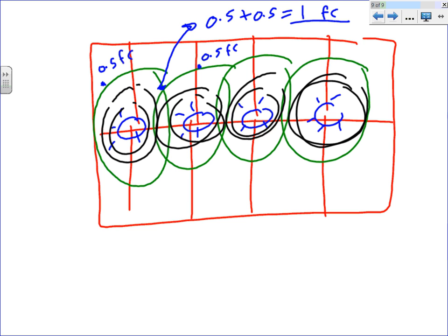The same token could be at this point, Mr. Rabab, right here. If I want to find the foot candle based on these curves, I would go 0.5 plus 0.5. That will get you 1 foot candle. Now, Spencer, if I have a third fixture to make things worse, and that fixture's curve also landed here with another 0.5, it becomes 0.5 plus 0.5 plus 0.5, 1.5 foot candle.